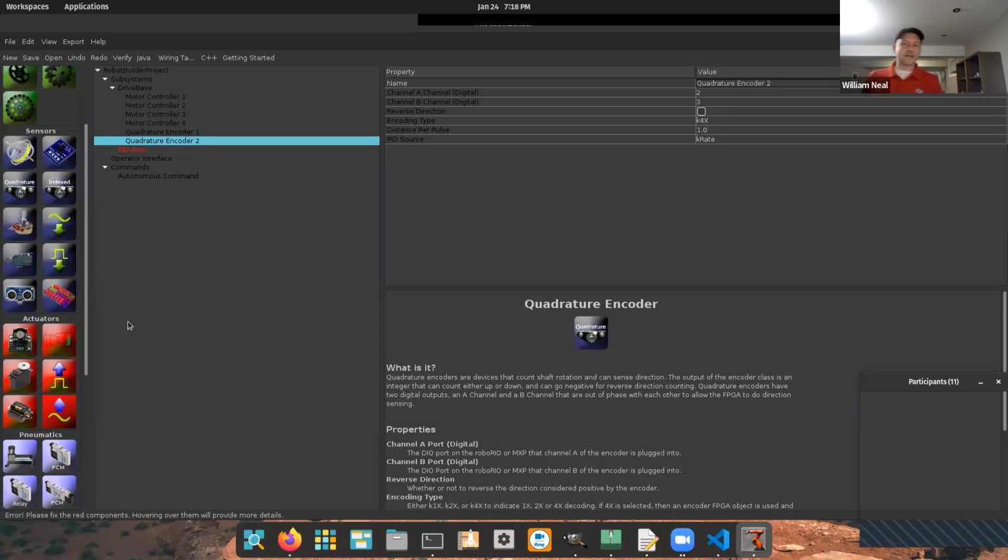These encoders tracked how far the left and the right side of the robot had traveled. And there we might consider one subsystem, the drive base, consisting of some encoders and some motor controllers. Beyond the motor controllers, of course, are the motors, but they're not directly tied with the logic of the computer programming, as the computer program interacts with the controllers.